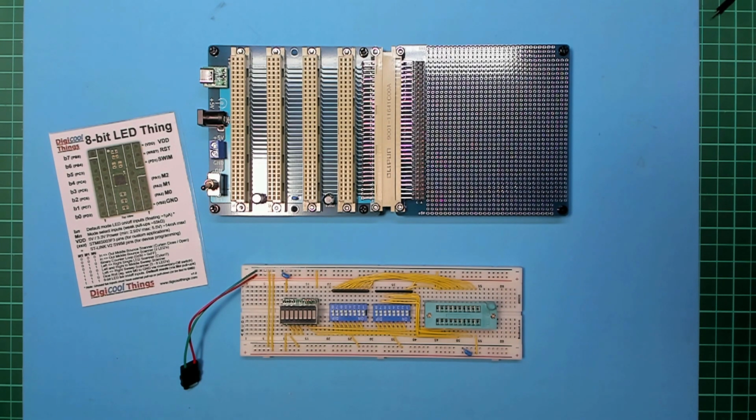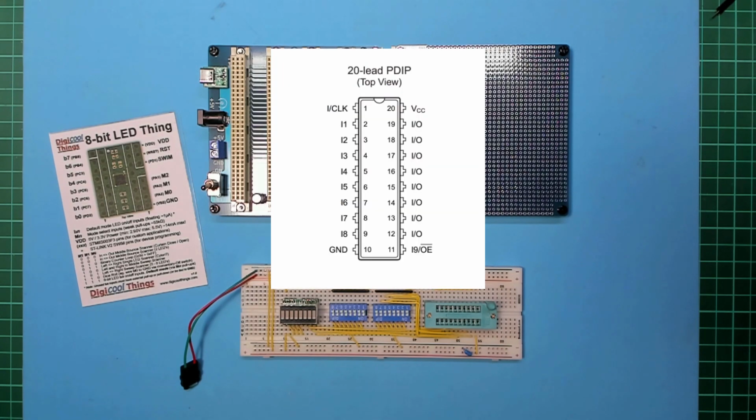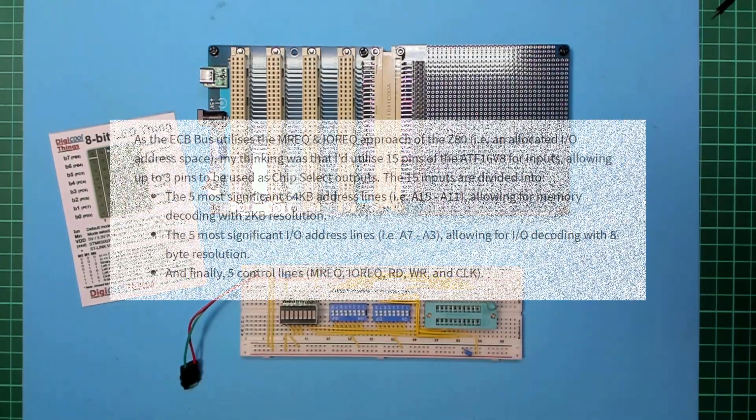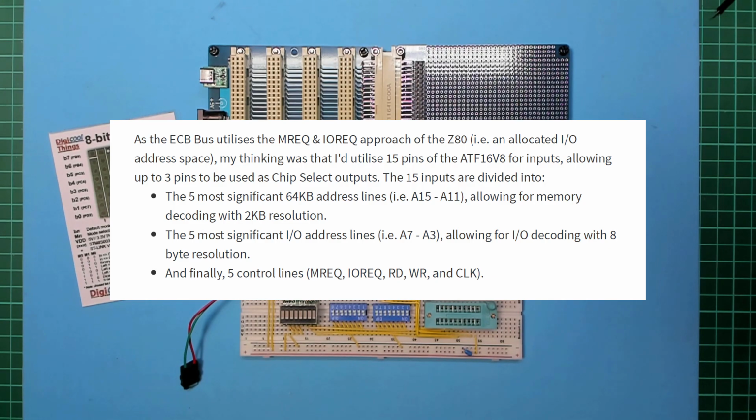The economical 20-pin dip packaged ATF16V8 appears to have all that we need. In its simple mode, this device has 18 pins available, 8 of which are I/O and 10 are inputs only. In simple mode, 2 of the I/O pins are permanently configured as outputs only, pins 15 and 16. As the ECB bus utilises the memory request and I/O request approach of the Z80, i.e. an allocated I/O address space, my thinking was that I'd utilise 15 pins of the ATF16V8 for inputs, allowing up to 3 pins to be used to chip select outputs.